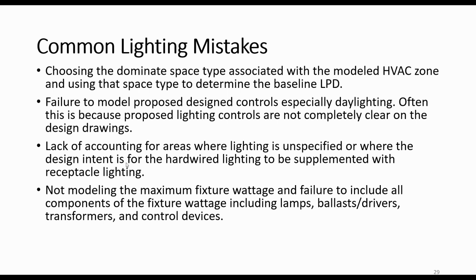And lastly, not modeling the maximum fixture wattage, and also failure to include all of the components of the lighting fixture. So you need to include the lamps, the ballasts, drivers, transformers, all of those need to be captured. So a prime example with fixtures is often a fixture may be rated at 60 watts, maybe because it's an older fixture model where people were using 60 watt incandescent lamps frequently. And so the fixture is rated at 60 watts, but the design is for 8 watt LEDs. Well, you'd have to model the 60 watt fixture, not the 8 watt LED. So that's a common mistake.